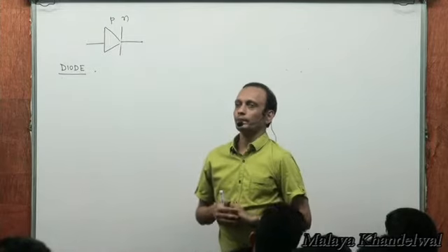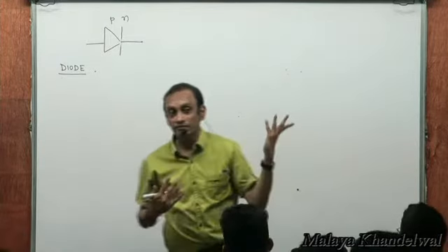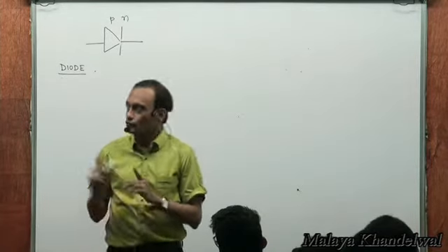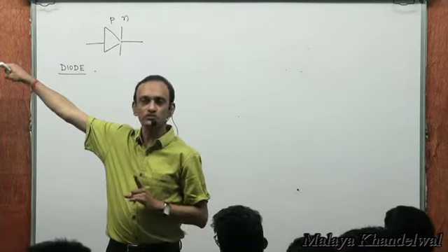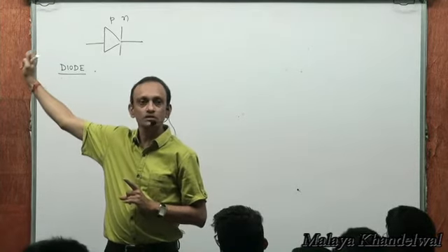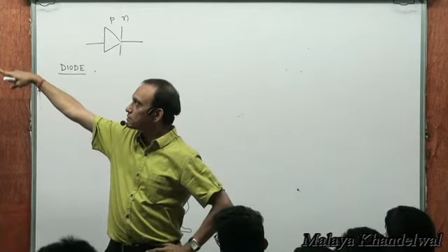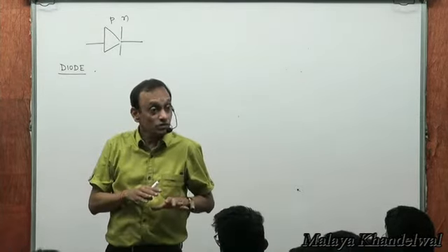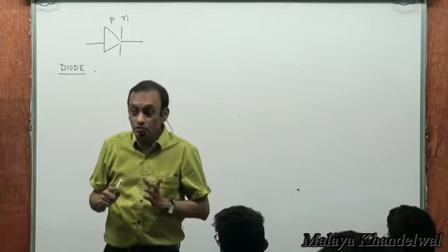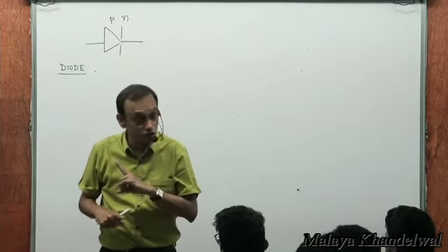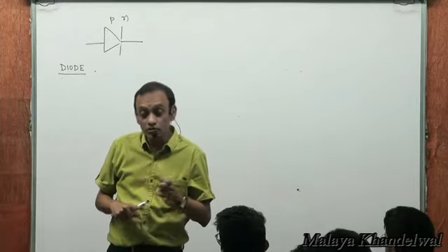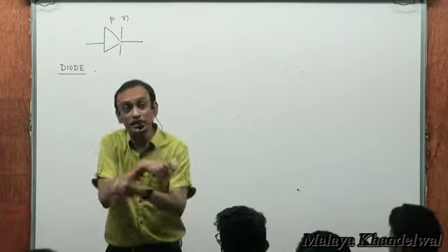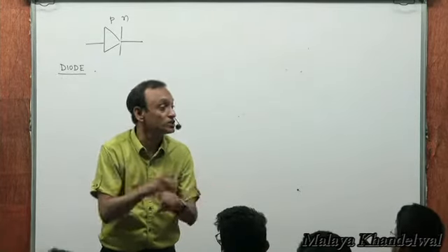Now, the other thing is that most power sources, for example, when you connect a socket here, is going to give you a sinusoidal voltage. It's written 230 volts, 50 hertz. What does it mean? 230 volts is the RMS voltage, and 50 hertz means those sinusoidal cycles, 50 cycles per second. 50 times it's changing the polarity.